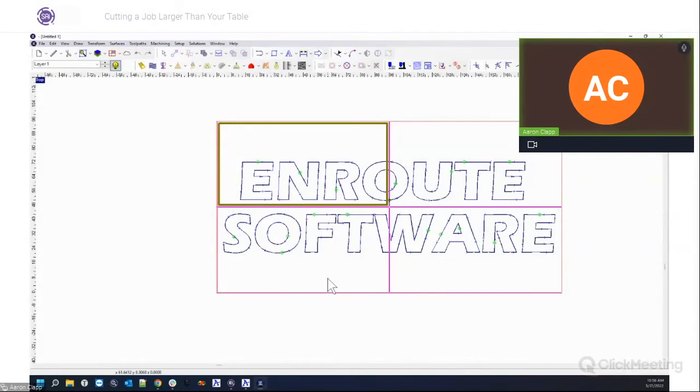Some folks, what they'll do is they'll drill a hole in their spoil board. If you don't have pop-up pins or anything on your machine that kind of helps you center something exactly in the same spot, it might actually be helpful to maybe create like a little jig or some little pins inside of your spoil board where you can shove something up into that corner and it always is in the right spot, and then do that for both sides.